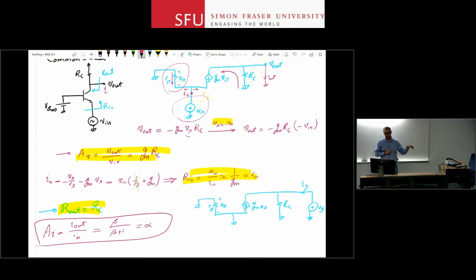And in that case, actually, the small input resistance is helping you. Because in RF systems, your impedances are always around 50 ohms, 75 ohms, depending on the standard. But they are relatively low, the characteristic impedances of your systems. And the low input impedance of the common base is not really a limitation in those situations. So the extra bandwidth that you get with this stage is very beneficial. So you use it instead of a common emitter stage.